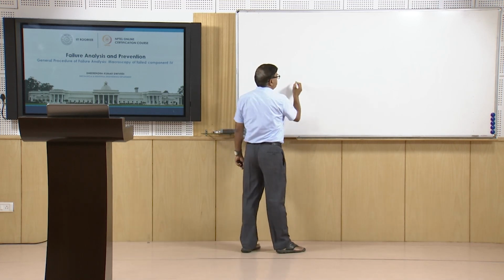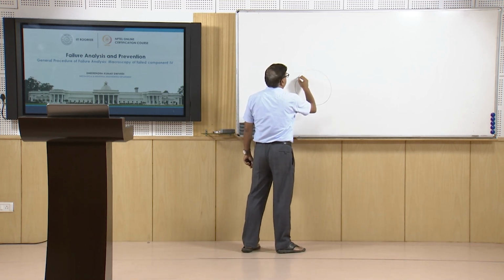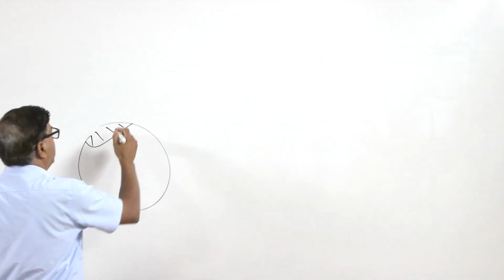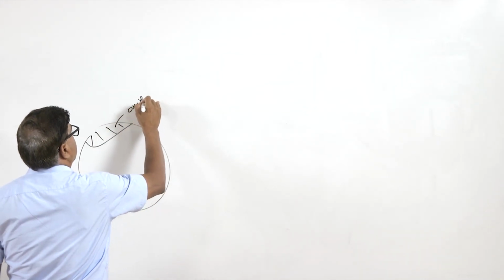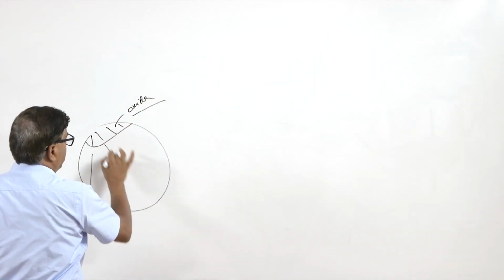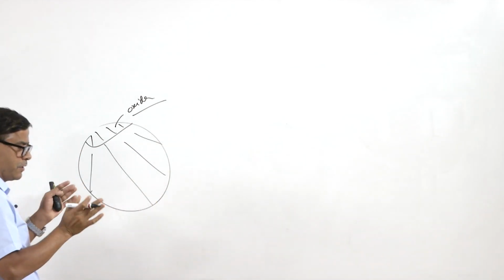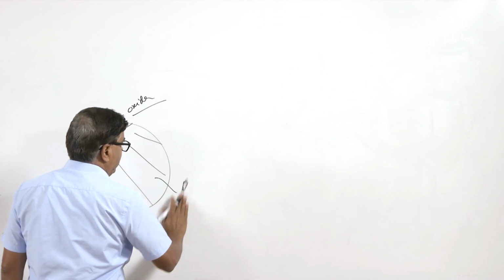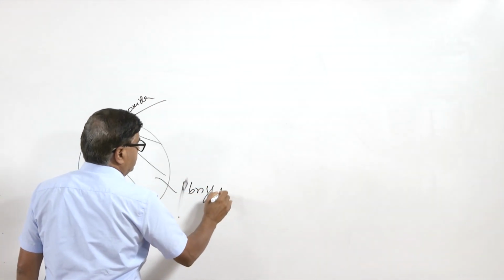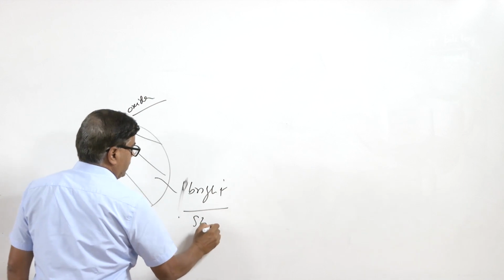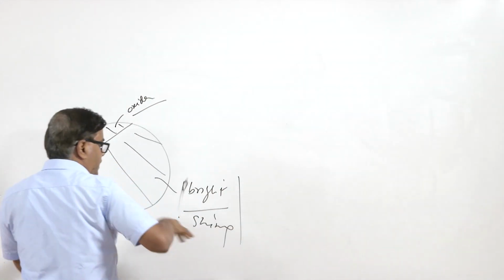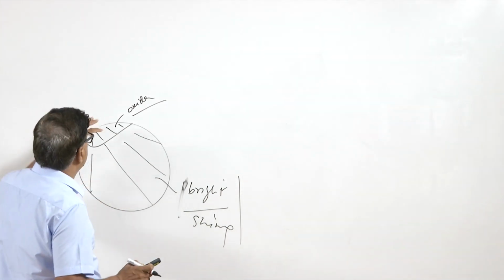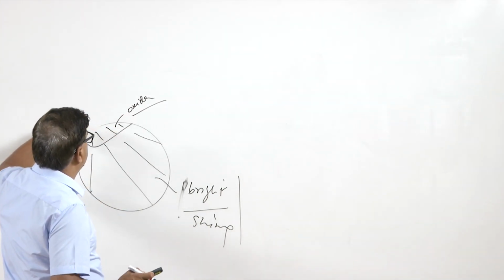There is one more possibility: if this surface was exposed in the environmental conditions for long, then it will get oxidized, and another part will be failing catastrophically under the overload conditions. So, this will be comparatively bright and shining. This will suggest the possibility of the freshly fractured surface.